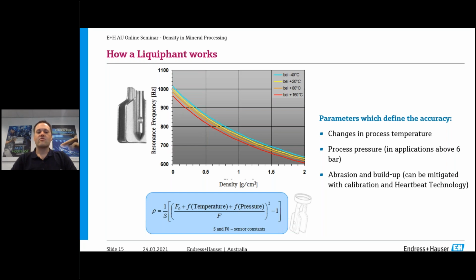And the good thing is that it's also very easy to calibrate, so as long as the device is continually calibrated. Because this is a contact device, which means it's in contact with the measurement, you can imagine a slurry would abrade the device. Depending on what type of slurry it is, we can offer different materials to maximize its longevity. Some of you might also be asking how long it would last in different processes, and I'll go through some specific examples in a minute.